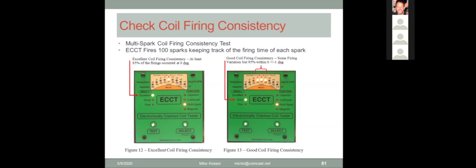And remember, we talked about there's a whole chain of functions that have to be working in concert: the timer, the wiring, the contacts, the carburetor. The timer has to be concentric on the camshaft. There's a whole bunch, and the timer has to be clean, have good clean contacts and no bounce on the contact. Chances are, if you have other variables contributing to your overall ignition timing quality, having the difference between good to excellent may or may not be noticeable at all.